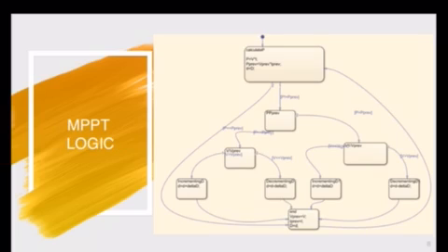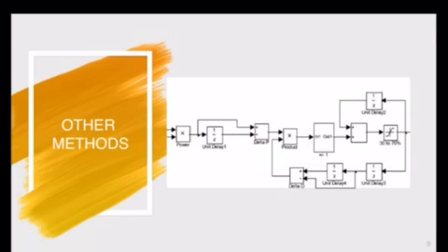The basic logic inside the maximum power point tracker is that it compares the current power output with the previous power output. Once you compare the power, you compare the voltage and change the duty cycle accordingly. There are two branches that result in an increase in the duty cycle. The other two branches, you decrement the duty cycle. If we only compare the power to determine whether or not to increase or decrease the duty cycle, we could do all the computations in the Z domain.